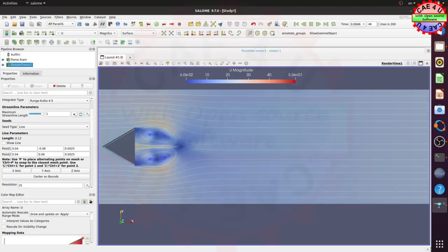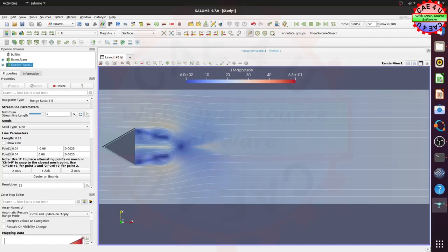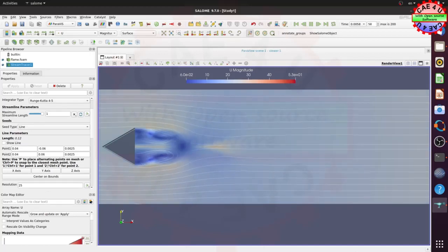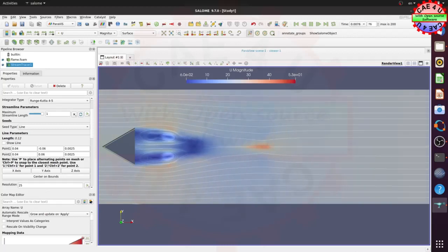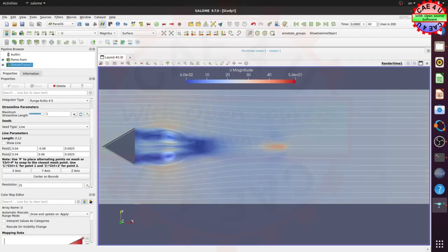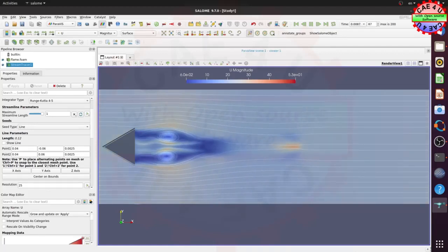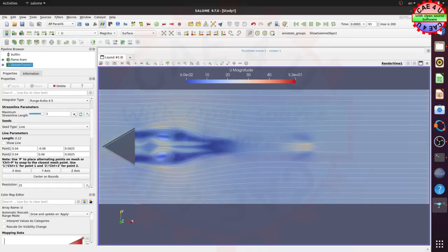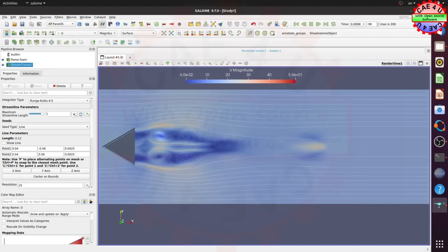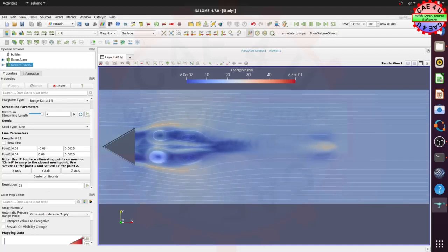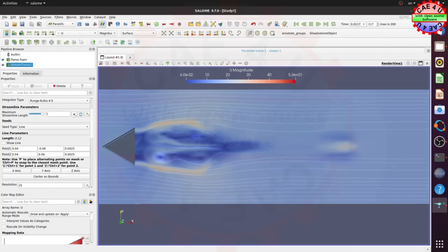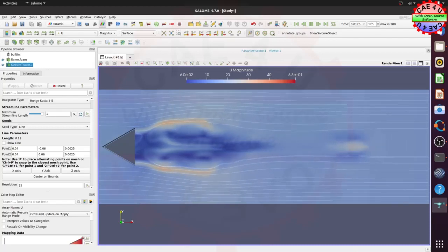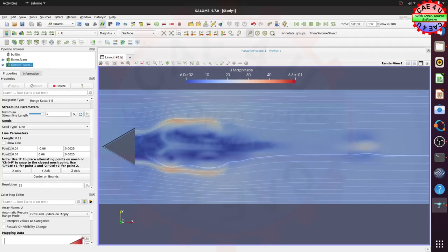To understand the ignition dynamics, the time for the run may be sufficient, but to know about the further combustion sustainability, the analysis should be run further. However, it is worth noting that the OpenFOAM solver offers promising options in terms of modeling such complex phenomena involving reactive flow and LES turbulence modeling.